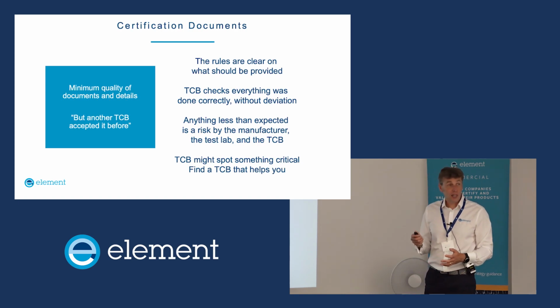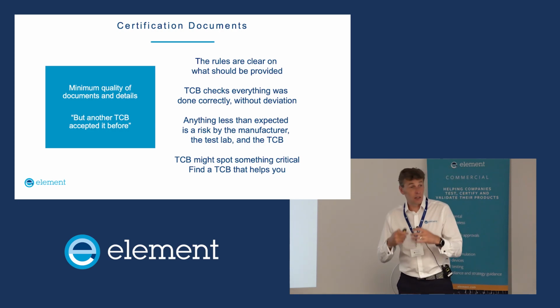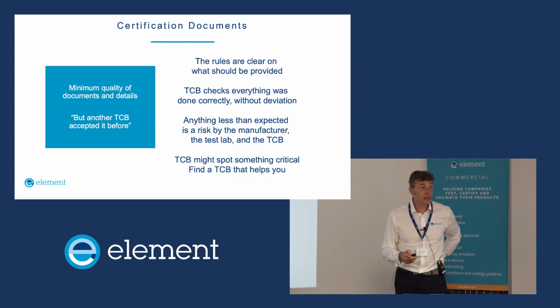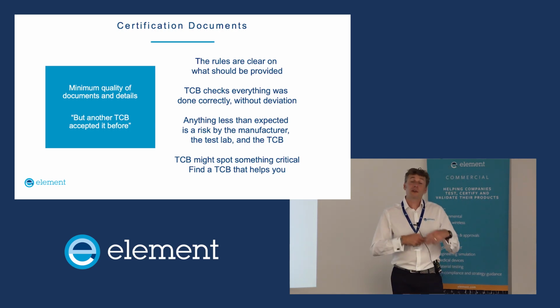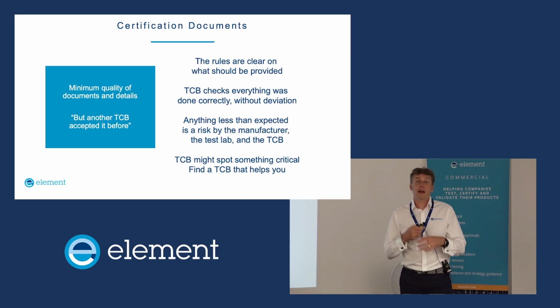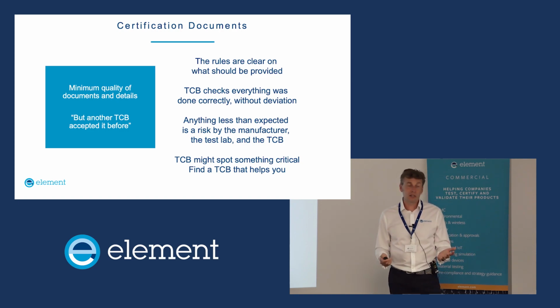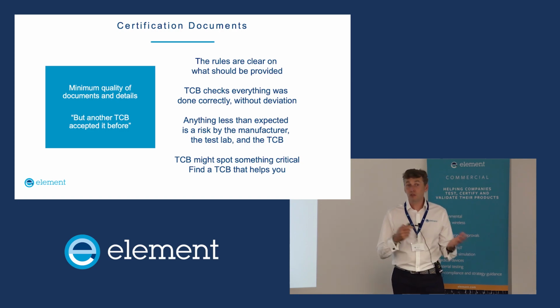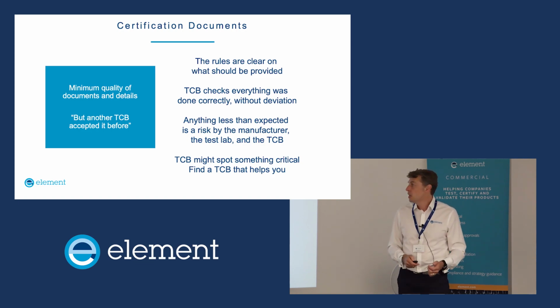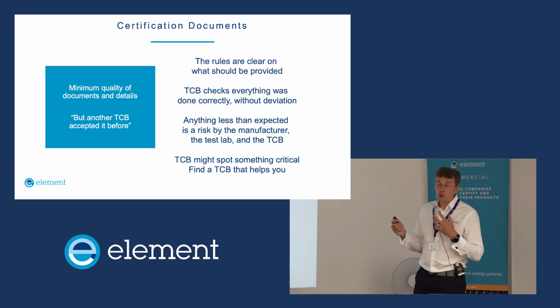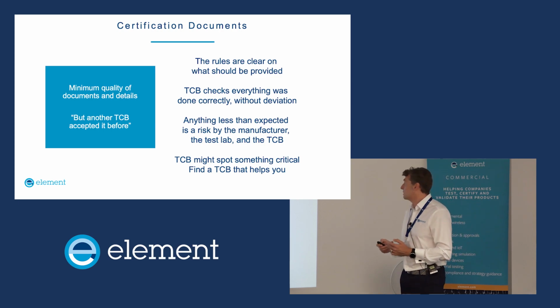When you go for certification with a certification body, has anybody here ever handled a project to a TCB or a certification body? A few tentative little hands there. So there'll be forms that you had to send in, and you'll have had to send in the documents. You'll have had to send in the block diagram, the parts list, the technical description, photographs, user manual, test reports, and there'll be certain quality of documents that you must send in.